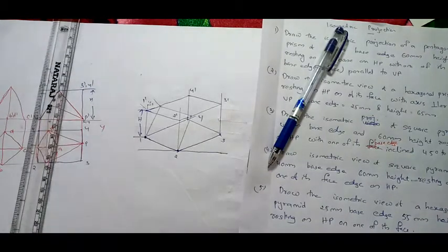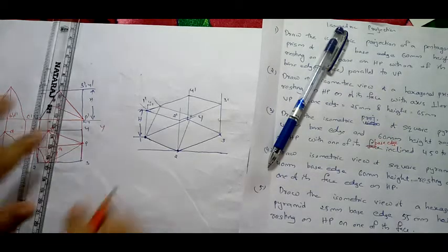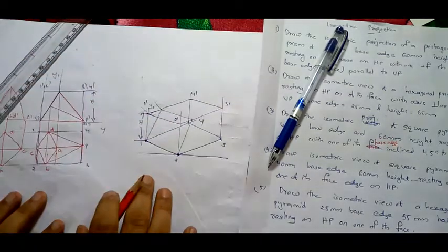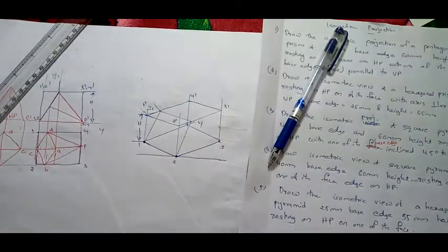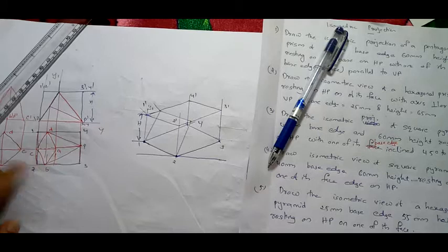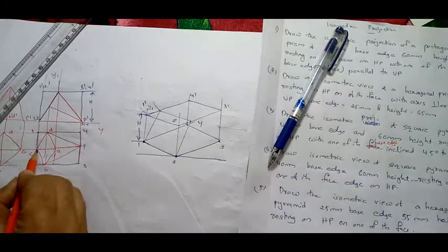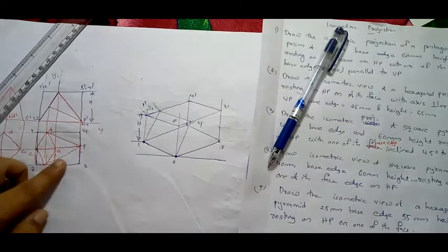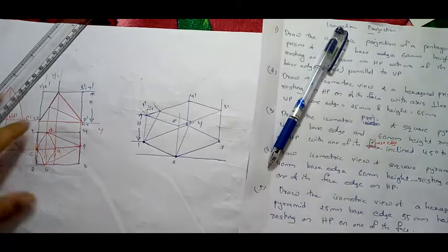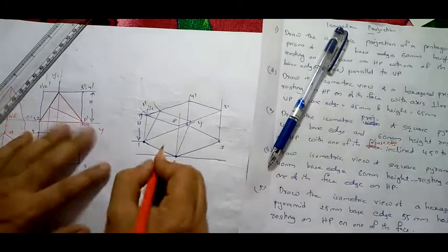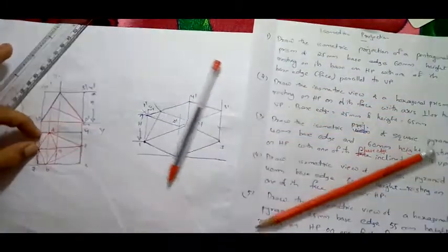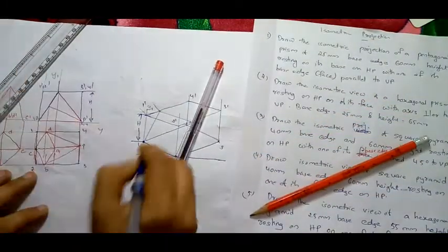Now I have to find the corresponding points. The same procedure I am following for all the problems, so kindly bear with this. After inserting this plane, next I have to cut these points here. They have to be cut on this plane, right? Now starting from the first point. See here, C. These 2 points you can easily cut. See, C is on 1 2, the midpoint of 1 2. So take this distance on the compass, cut it here, and you will get C here.